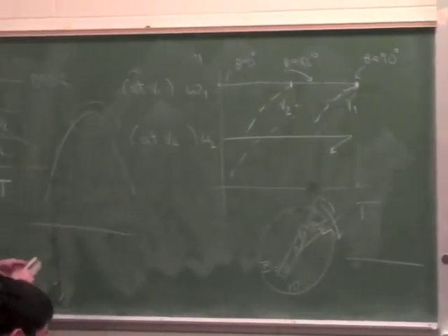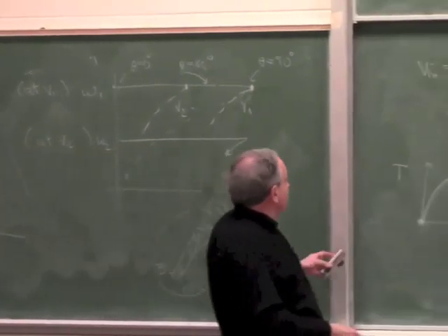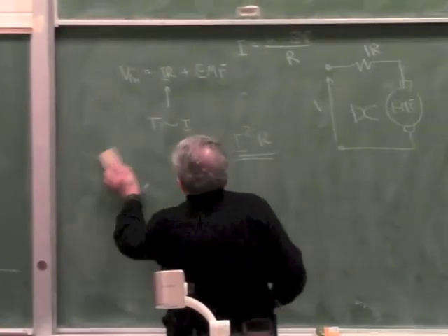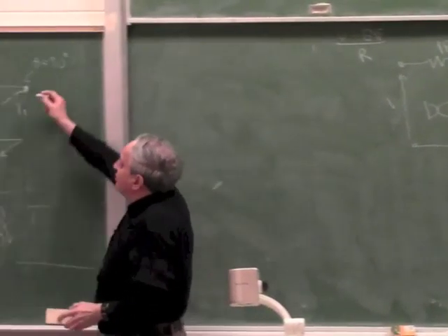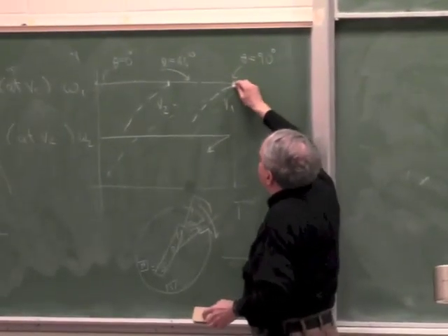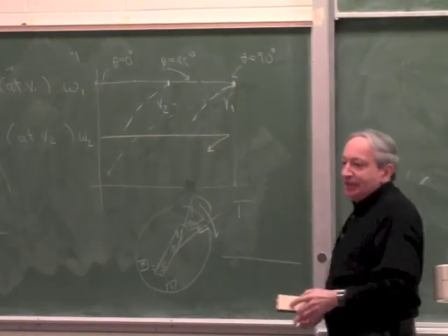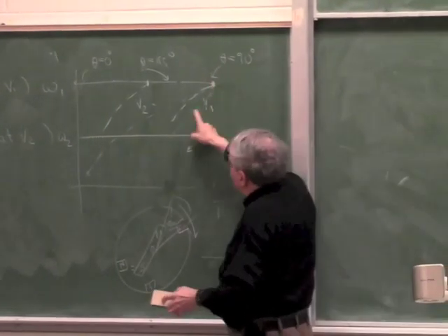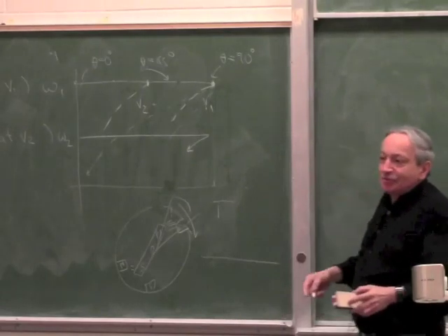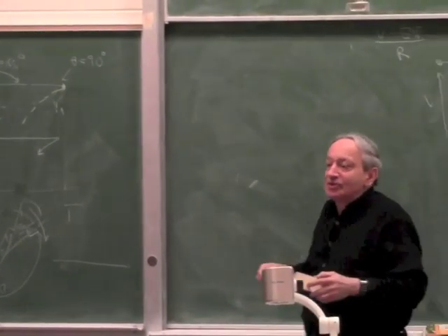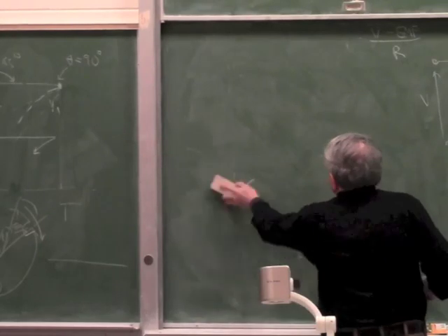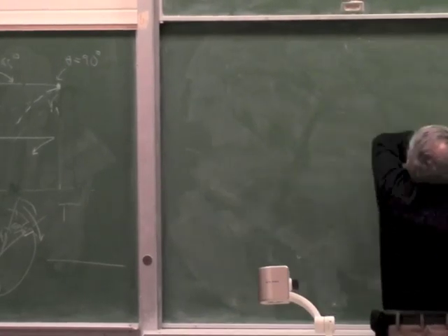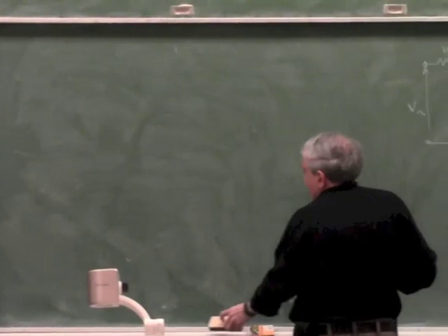And now if we make a family of curves for an induction motor, it's a little bit different, because unlike a synchronous motor, which cannot take any bigger load and it collapses, an induction motor, this curve actually exists. Because an induction motor doesn't lose all the torque, it just starts slipping more and more. So because of that, it's a bit different and has a more desirable characteristic.